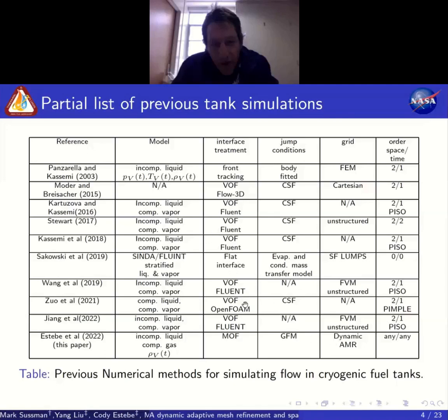So our approach is to model the gas using a so-called low Mach number approach, where, in the results that I present, we assume that the density is spatially constant and varies only in time. The temperature and the pressure can vary in space and time in the gas.